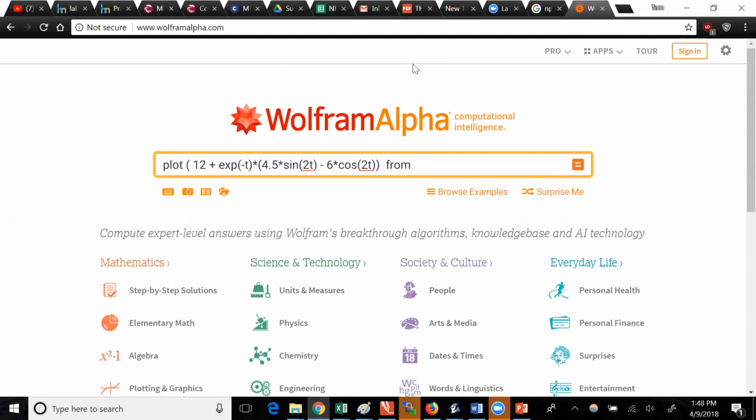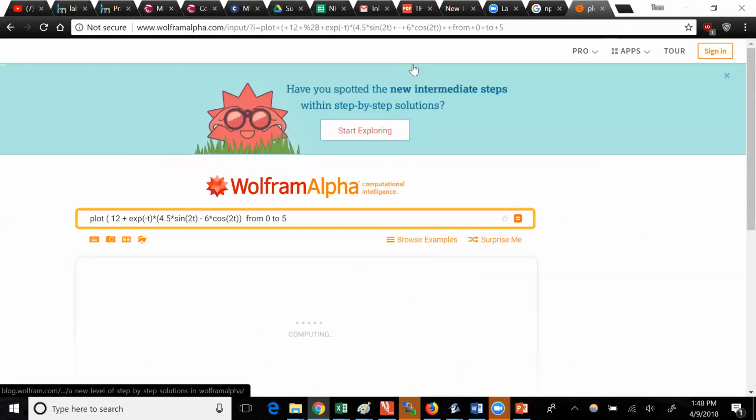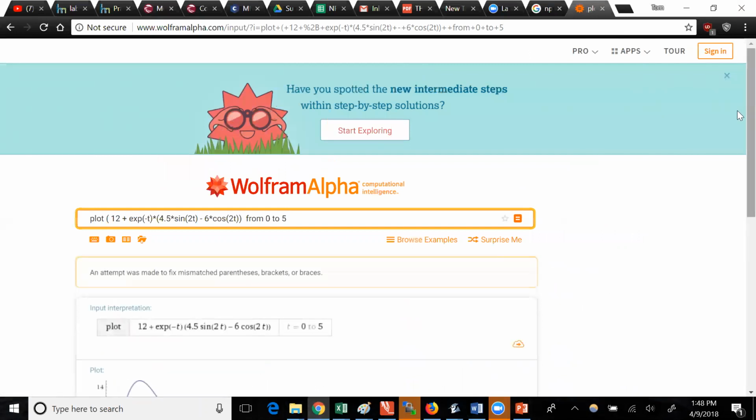And we want to go about 5 time constants or so. The time constant here is 1 second, right? So if we go out t from 0 to 5, that should give us both the picture of the transient and the final value.